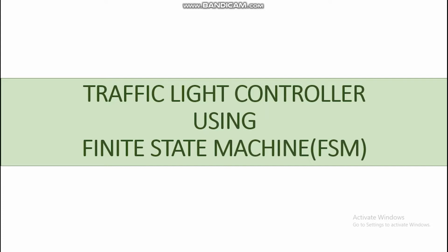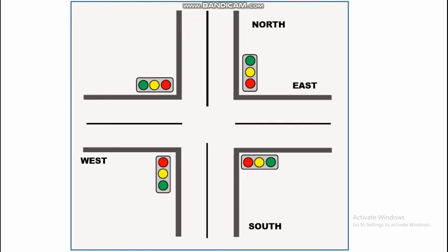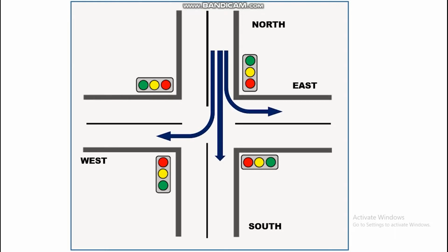Before explaining the implementation of the project, let us see how the design will work. The controller is designed for a 8-lanes 4-way junction. It will let the cars from north to pass first. Cars from north will be able to go all the other 3 ways. For this purpose, the traffic light on north side have to be green and the other 3 sides have to be red. This state will remain for 8 clock cycles.